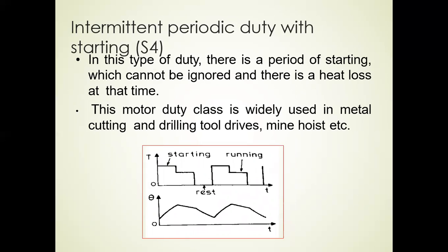Intermittent periodic duty with starting. In this type of duty, there is a period of starting which cannot be ignored, and there is heat loss at that time. This motor duty class is widely used in metal cutting, drilling tool drives, mine hoists, like that.